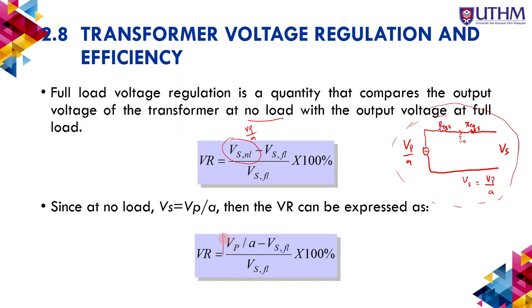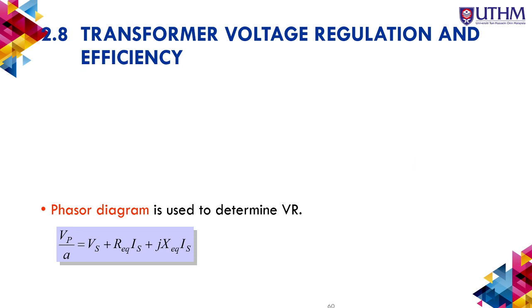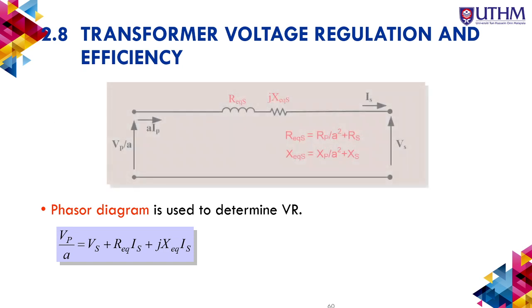It is easier to calculate, because sometimes during the test they don't mention the no load voltage. They just mention the full load voltage, which is the given supply.